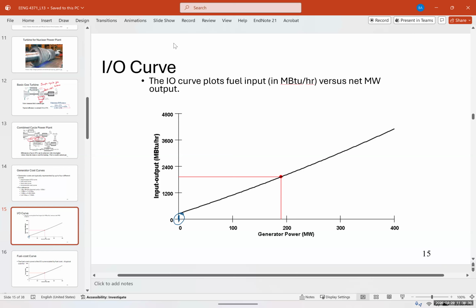Again, louder. Yes. Startup and just to maintain steam pressure. It represents the consumed fuel just to keep the plant running. It's like just to keep everything warmed up, because until the water reaches 100 degrees Celsius, you won't have any power generated, okay? So imagine you have cold water, you're not generating any power, but you're still consuming fuel, okay? And it's going to be very inefficient if you do that.